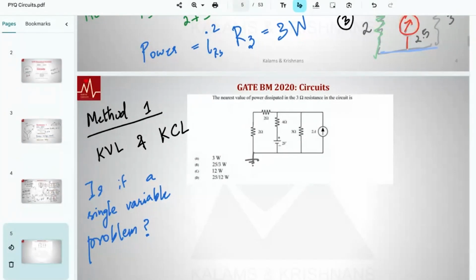If I put the ground here, or if I put the ground here, does it matter whether I put it here or there? It's all zero. Notice, this is all zero. Where I put the ground doesn't really matter. This is all of the same voltage. They're connected by wires, negligible resistance as far as the rest of the circuit is concerned. Where you put the ground is immaterial at the bottom.